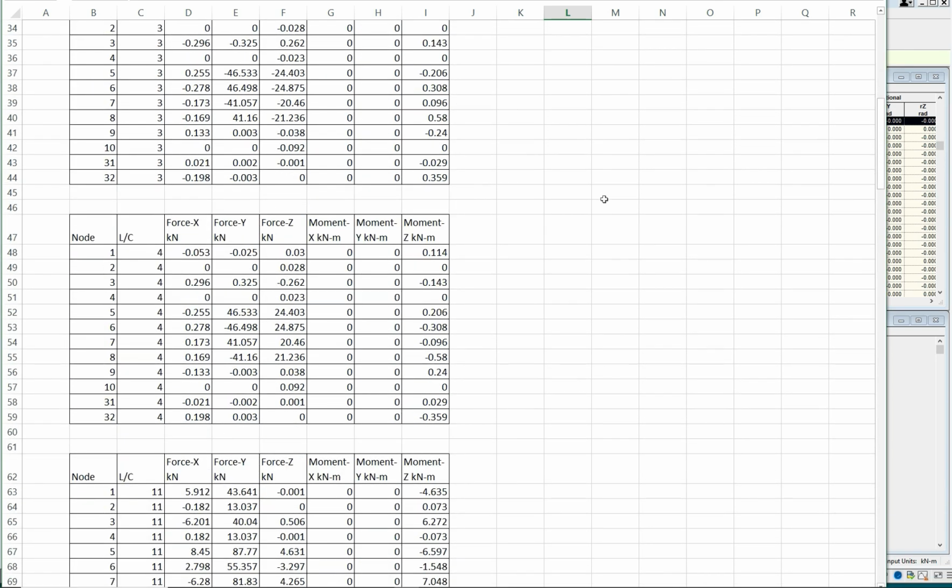Note that we have not taken the response spectrum primary load cases. Taking only static load cases is adequate, because the response spectrum will give results only in the positive direction. It will not give results with negative signs, and wherever there is an uplift, we need a negative sign. So it is better to design the footing with reactions obtained from static earthquake cases.